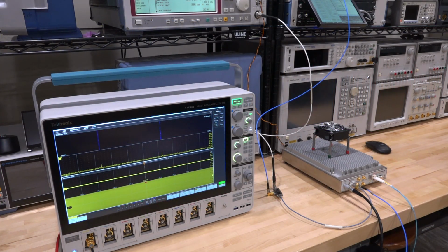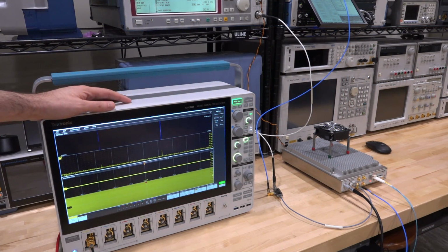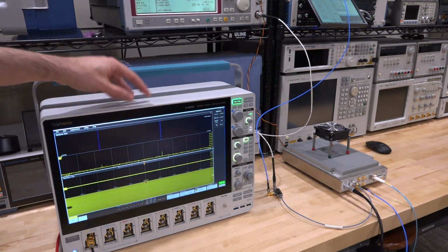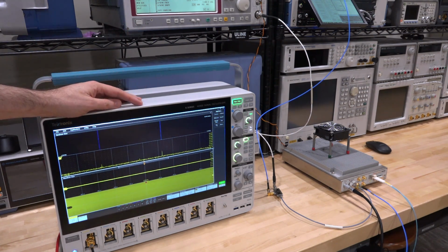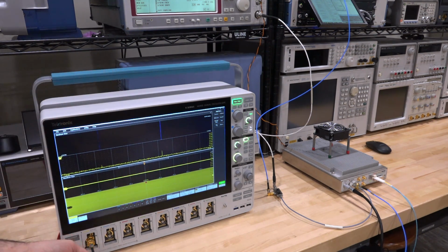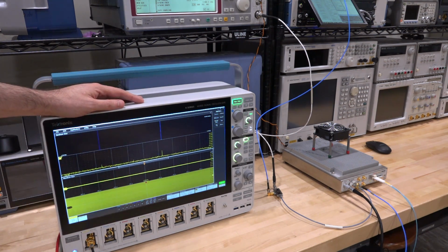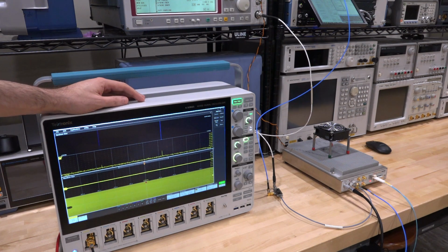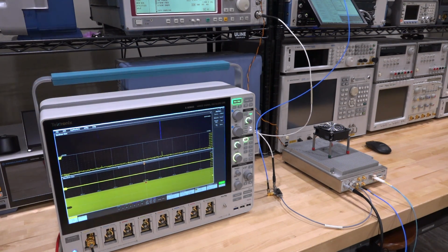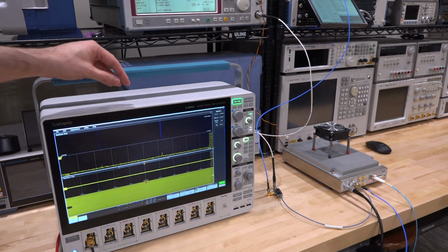So now let's take advantage of the Tektronix 6 series to do a similar type of digital down conversion analysis. The Tektronix 6 series has a lot of functions that take advantage of the DDC, and it can do some pretty neat analysis directly in the instrument. I'm basically connecting the wideband IF signal to channel 1 of the Tektronix, and we're going to experiment with a different kind of waveform. What I've loaded from the M8190 is now a very rapidly frequency hopping signal. It hops over 300 megahertz very, very quickly, still centered at 28 gigahertz. This is now beyond the analysis bandwidth of the SM435C, which means that we can use the IF output and go over here to analyze it.